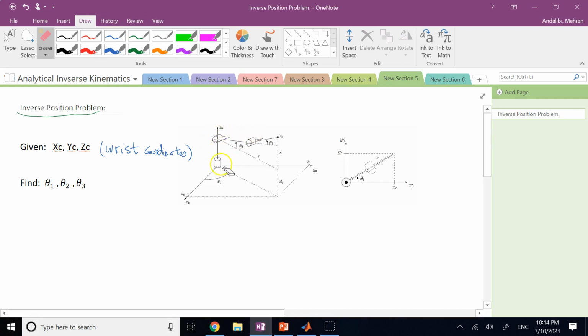robot is the first three joints. In this case, it's just RRR. All of them are rotary. But even if the first three joints were not RRR, like RPP or PPP, or RRP, any of those formats, Cartesian, cylindrical, spherical, or articulated like this. There were four major versions, if you remember from the first lecture, which was a categorization of the robots based on the first three joints.